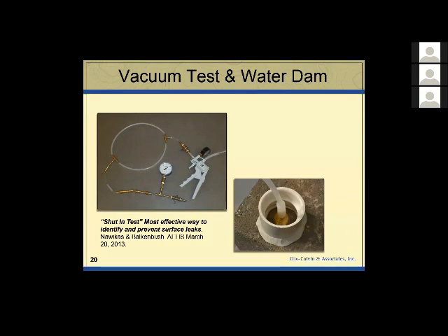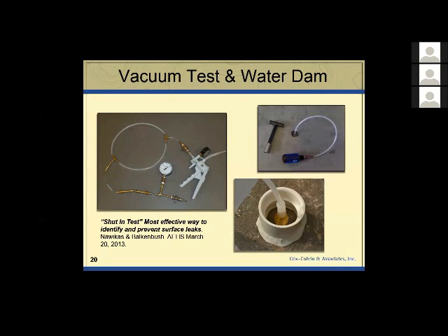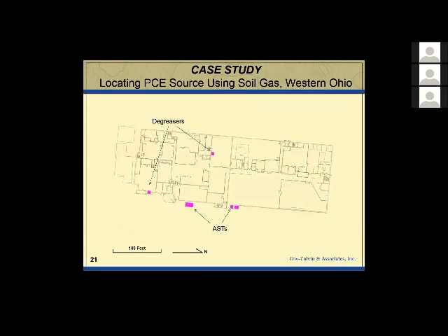As to the point going through the slab, you surround it with water. There's a stick-up point on the right. I just surround it with distilled water using a piece of PVC pipe and some Play-Doh. If I have a flush mount, then I can pour the water directly into the 1.5-inch hole. If you don't lose the water, it didn't leak. And if you have good hardware, you won't see any leaks. I've never had one using this device.